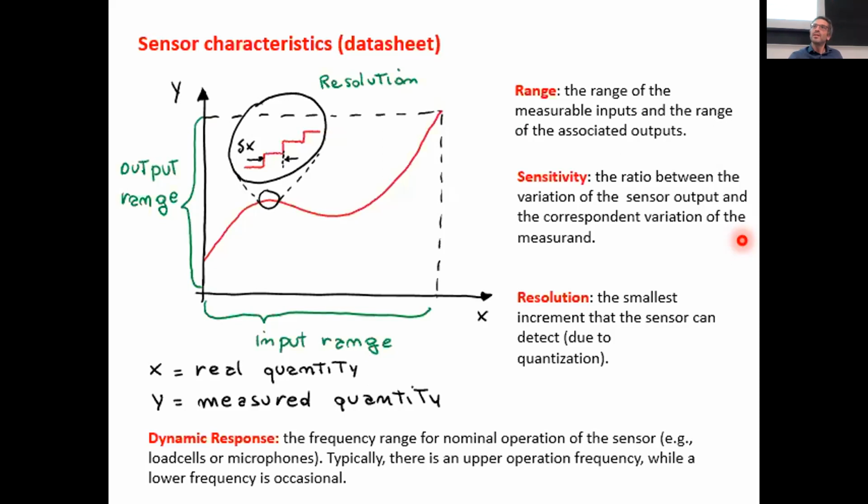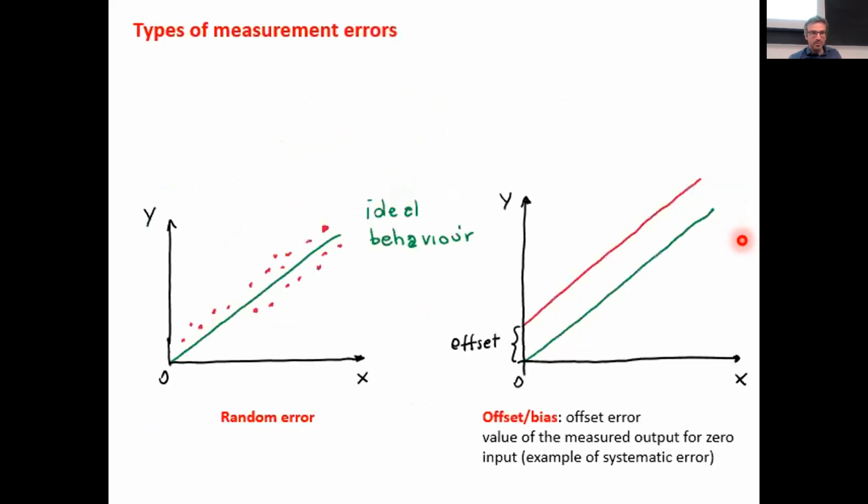Like if you hammer a piece of metal or link, and you want to see the very fast peak due to the hammering, you can detect it up to a certain frequency, because a hammer is like a flat spectrum input, so it contains all the frequencies, but the load cell will be sensitive only in its dynamic range. The other frequencies will be filtered out.